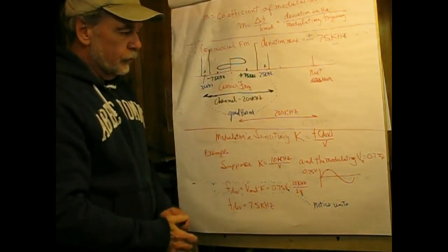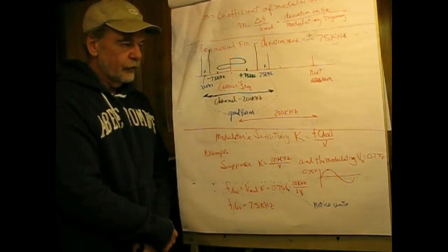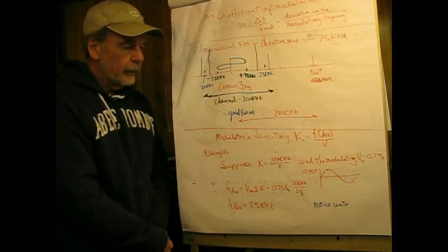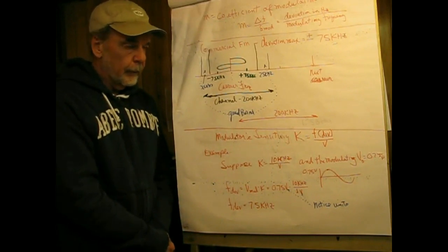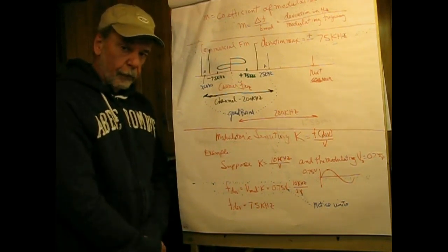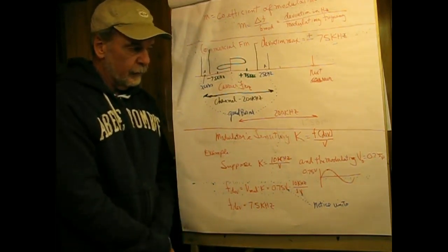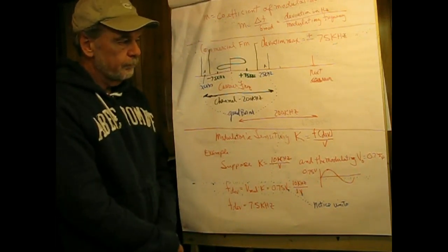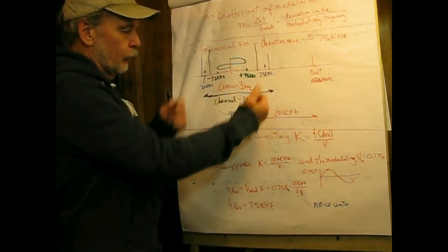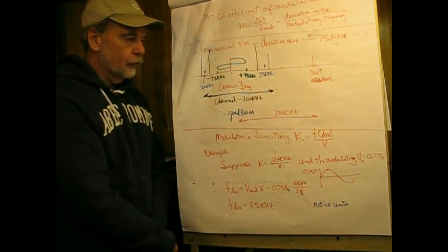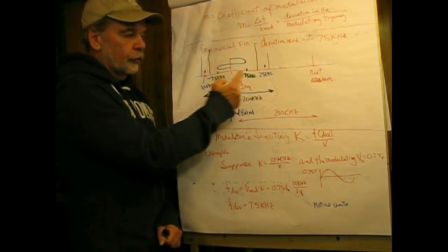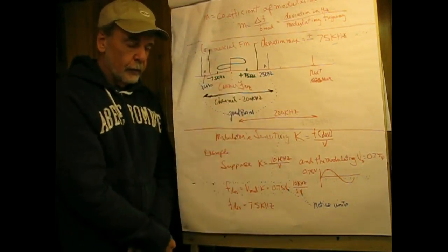So the FCC usually does not assign adjacent channels, and the same is true with AM and with television for that matter, in the same city. But like I was picking up skip before, that can happen in FM to a little bit lesser of a degree because of the higher frequencies. So that's the channel bandwidth here, sits in at 200 kilohertz. And ideally it should occupy 150 kilohertz with regard to the deviation of the carrier.